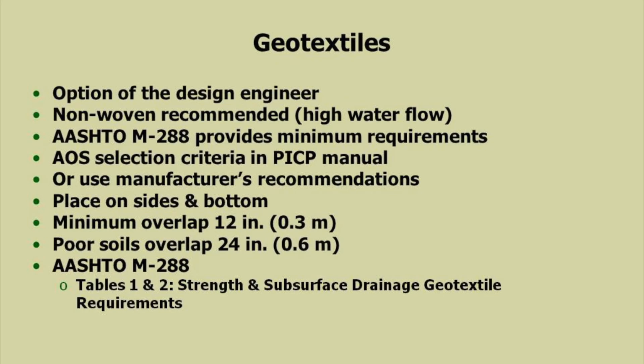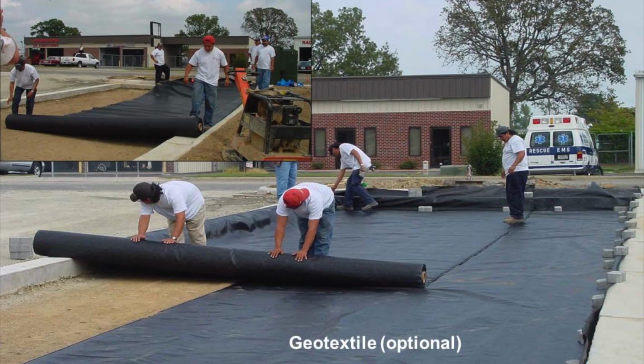Some discussion earlier about geotextiles. When do we use geotextiles or not? Here's some guidance. If you download these slides, you can get the suggestions here. There is an AASHTO bulletin, the AASHTO M288, that's in the ICPI design manual. Referenced in there, it talks about specific selection when you do want to consider that, or if you do. I'm with Chris and the others that have been mentioned. I don't think you want to unless there's some reason, but the industry guidelines typically tell you to overlap geotextiles.